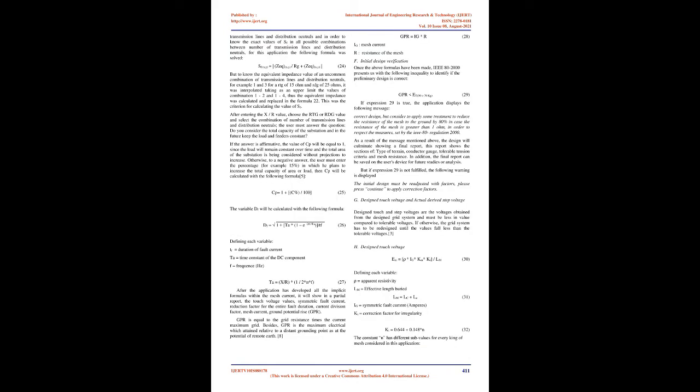If it were the case of an L-shaped mesh, you must enter greater and lesser length and width values, that is, for values and their respective separation distances. To calculate all the variables involved in the mesh current, the user will enter the value of the X/R ratio depending on the characteristics of the substation.